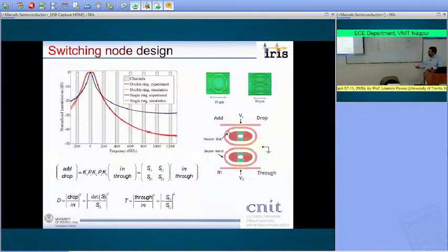The first one is that we reduce significantly the crosstalk, so we increase the isolation, as well as we have a transmission of the two ring resonators which has a flat top shape, meaning that we are not deforming the light signal that is propagating in the desired channel.